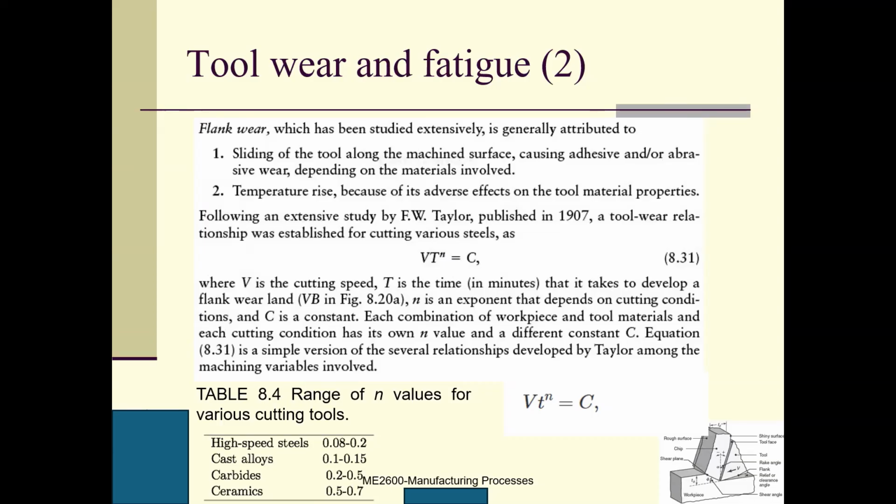Don't panic if we use this equation, and don't panic either if we use that equation. The same authors just give us two different equations, but they are the same. This range of n depends upon the cutting tool material. For different materials, we have different exponent values.